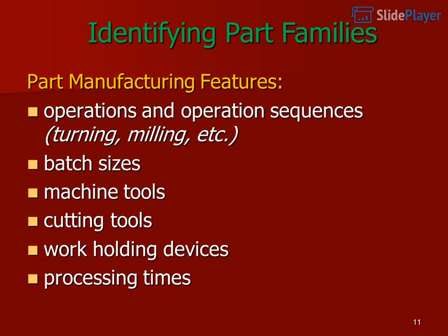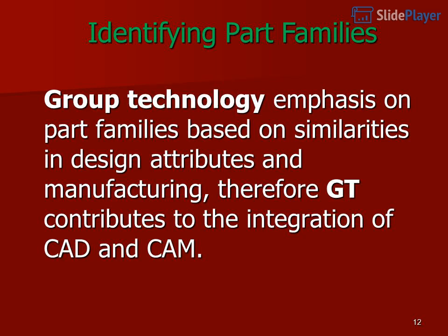Identifying part families. Part manufacturing features: operations and operation sequences, turning, milling, etc.; batch sizes; machine tools; cutting tools; work holding devices; processing times. Group technology emphasizes part families based on similarities in design attributes and manufacturing. Therefore GT contributes to the integration of CAD and CAM.